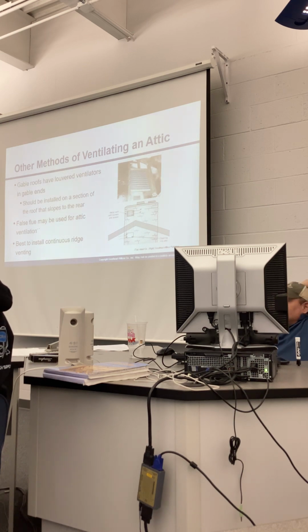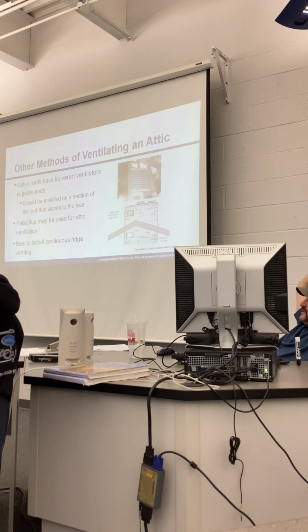And I would assume, guys, here's another advantage to foam and to what I just said, cement insulation. It is considered structural. So if you figure it into your engineering when you're building your building, you can put less studs, you can put studs further apart, you can load more weight onto a wall that's insulated with foam, because it is closed cell. Open cell is not considered to be structural, but closed cell is considered to be structural. So it actually makes your building stronger by having it in there. Does that make sense? Where fiberglass doesn't.